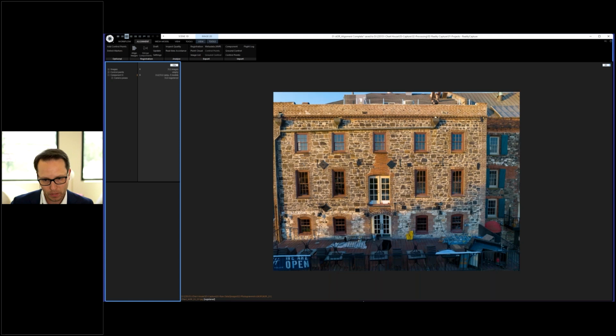It's the same as when you're registering your scans. If you do scanning, you break your registration into sub-registrations and then bring those together in a master registration. The same workflow applies in RealityCapture. You're going to use your components as your sub-registrations. We start from the small areas, and we end up with the entire project at the end: the master registration, or the master component.